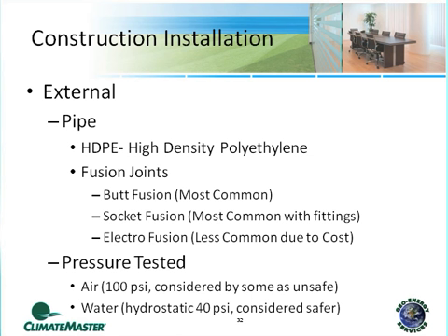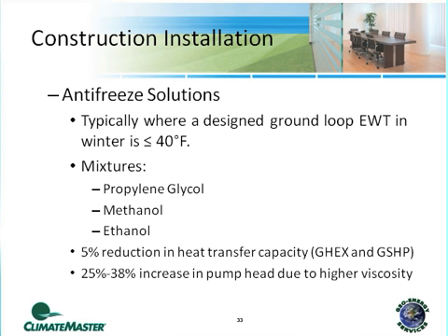Generally speaking, the industry recommends that you do hydrostatic or water pressure testing to about 40 psi. It's actually a lot safer because if that pressure were released, it would dissipate very quickly and wouldn't hurt anybody if they were close by. But there are situations where guys like to run 100 psi air pressure, and that's their prerogative. Just generally speaking, it's not the best practice.